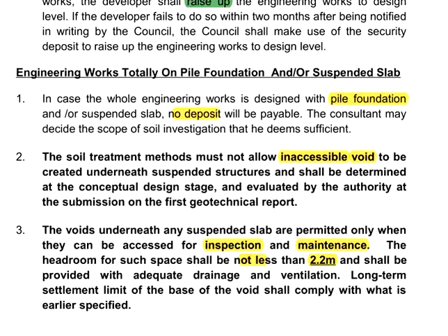Now, if the voids are required to be accessed for inspections and maintenance, for example, where they do not like to run the services over the suspended slab system, some architects may choose to run the services underneath the suspended slab system. This may require inspections and maintenance of those services. Now, in this case, the headroom for the space should not be less than 2.2 meters, and appropriate drainage and ventilation are to be provided.